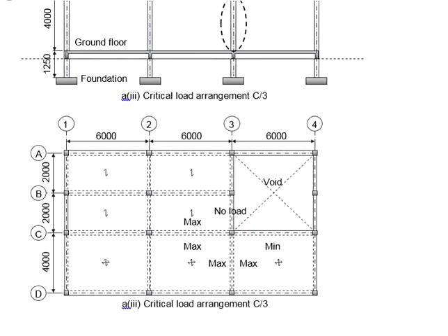Not only that, we will need to look into this frame also. Due to the one-way slab here, there won't be any loads acting onto this beam. To generate the largest moment possible in these directions, you will need to make these loads maximum.